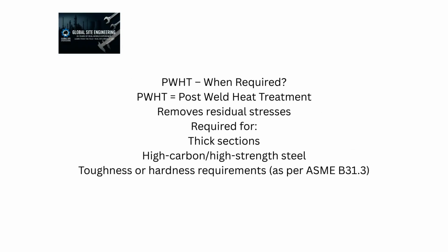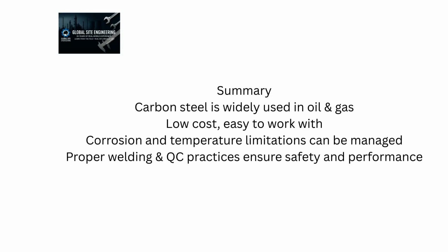Post-weld heat treatment. Post-weld heat treatment, or PWHT, is used to relieve residual stress and improve toughness. It's required when welding thicker materials, high-carbon steels, or when codes like ASME B31.3 mandate it due to toughness or hardness concerns. So to wrap up, carbon steel is tough, versatile, and budget-friendly, which is why it's everywhere.